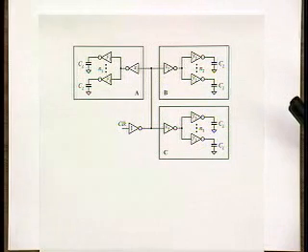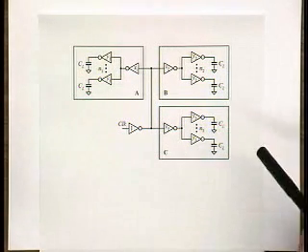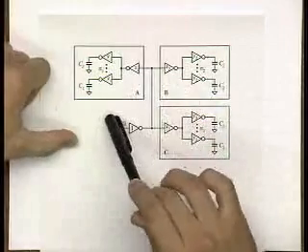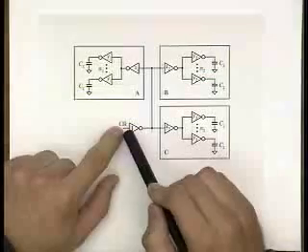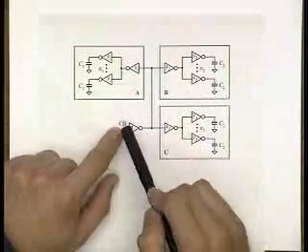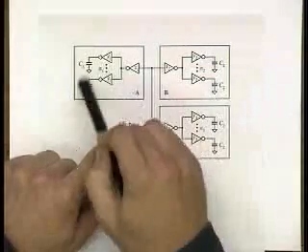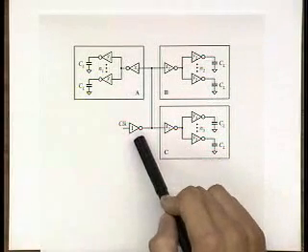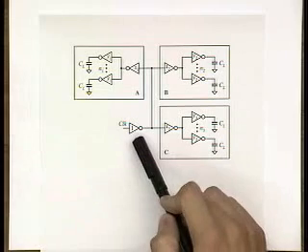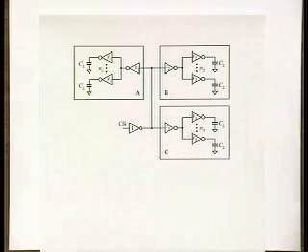And so the first question you will be asked is to pick the sizes of all these buffers such that you have minimum insertion delay, so-called. That's simply the propagation delay from the clock to all of your nodes. Now, we know that minimum delay comes at a certain cost. It's the highest performance you can get, but you're burning too much energy.